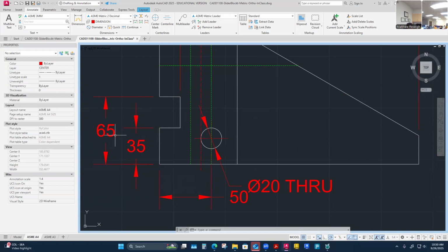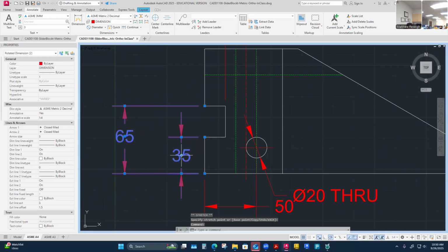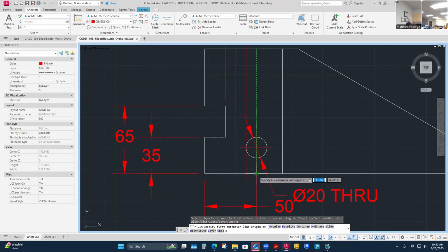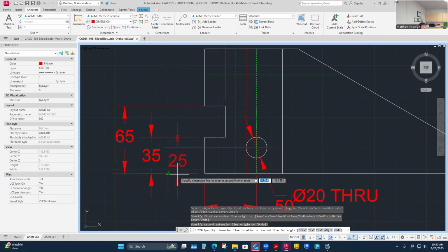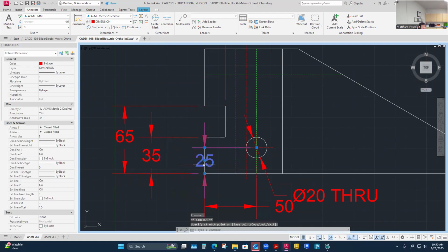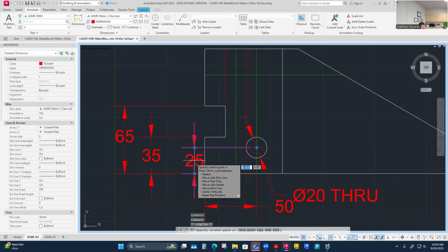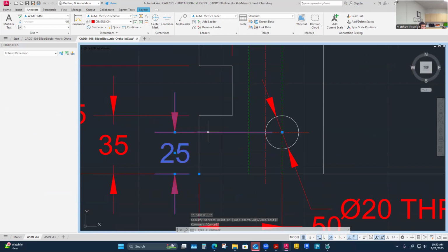The other location is going to be up. So I think I'm going to move these out. I think I did put a 10 millimeter on the 35, but I think I'm going to get it out of there now because I feel like this is the other dimension I want, from kind of this corner out to this center, but I'm going to pull it this way. So that's going to be probably the most intermediate dimension. It's probably the one that I could base my 10 millimeter on, but really, I generally don't do this until I'm ready to, and if it still crowds it at 10 millimeter, I'll pull it away a little further even. And then I'll just adjust my extension lines a little bit.